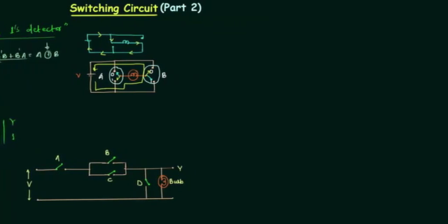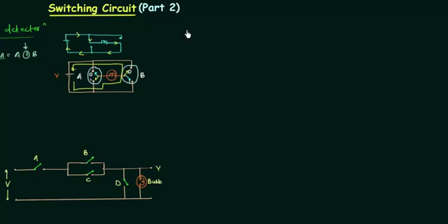Now we will move to the XNOR gate. And for XNOR gate, we have to take the complement of the XOR. It's very simple. A, B are the two variables, the switches that we are using. Y is equal to A complement B complement, or A B, and this is represented as A XNOR B. This is the representation for XNOR. Once we are done with XNOR, we will solve an example that will give you an idea how the question is asked in exam from this topic.